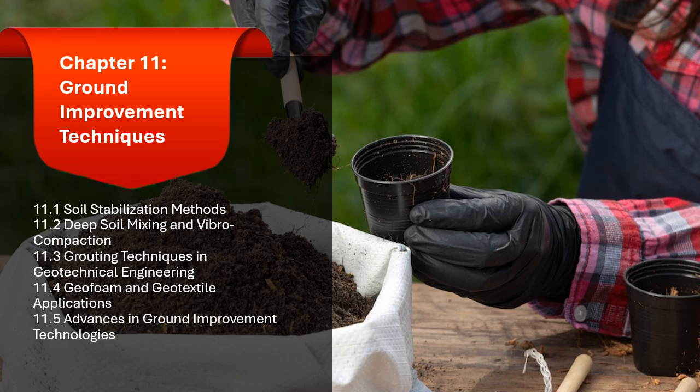Conclusion. Both deep soil mixing, DSM, and vibrocompaction are essential ground improvement techniques that offer unique advantages for enhancing the properties of weak or unstable soils. While DSM is primarily used for improving cohesive soils and providing a solid foundation for structures, vibrocompaction is most effective in densifying loose granular soils, particularly in seismic zones.